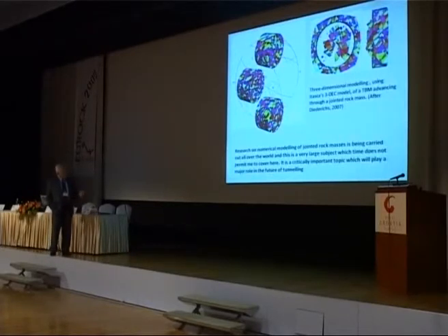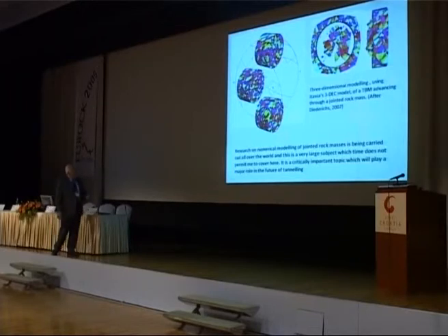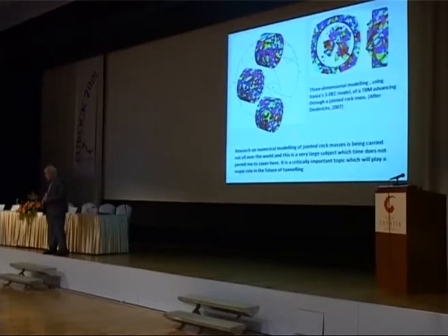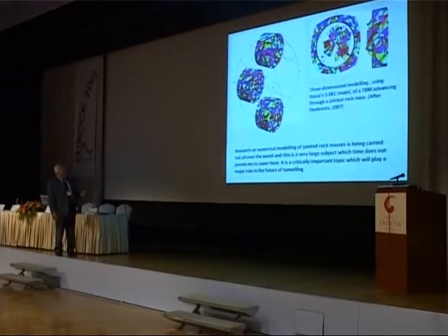This is a 3-dimensional model of a TBM going through a jointed rock mass under high stress. The issue here was what kind of blocks are loosened and can fall out at the face, because the TBM cutter needs a good clean bite at the face, and if blocks fall out, they have to be crushed before the machine can actually do any cutting. And so this is an illustration of some of those blocks that have fallen out. This is not a trivial exercise.